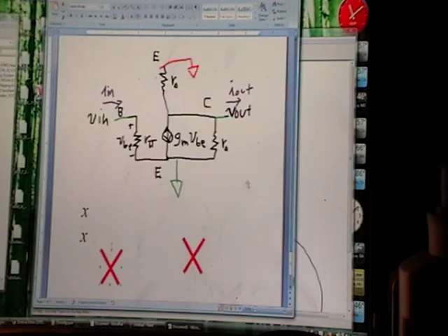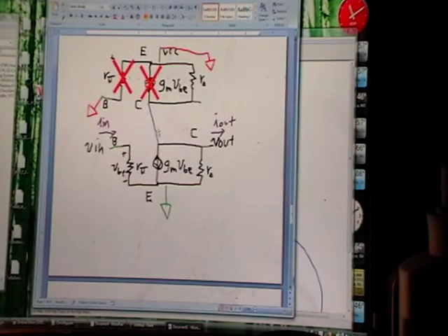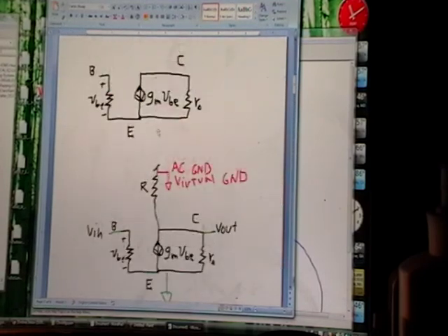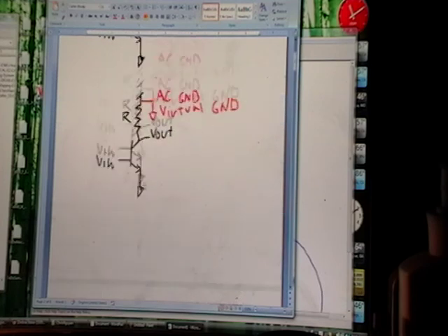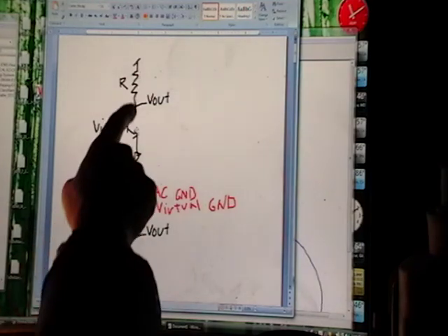Now the difference is, if you remember, if you have a big R right here, it can force your transistor into linear, or you can raise the supply voltage to keep that from happening. So if you have a resistor very big at all, like I said, either you have to raise the supply voltage or you face the danger of putting your transistor into linear.